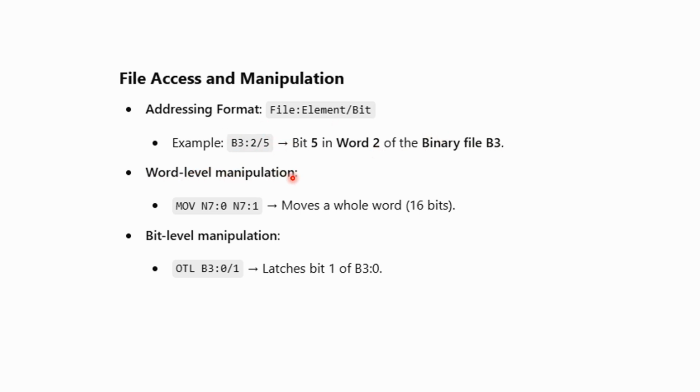And word level manipulation, say if I had a move instruction, moving N7:0 to N7:1, that's moving an entire whole word of 16 bits. And then with bit level manipulation, you have the output latch. An output latch for B3:0/1 latches bit 1 of B3:0.